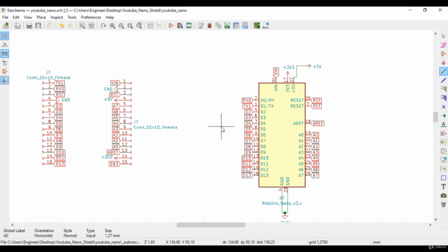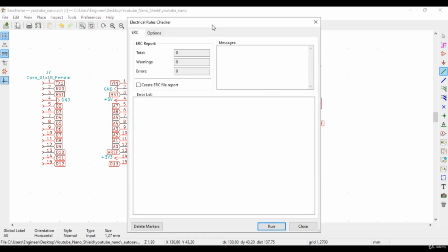Let's see if there is a mistake. That's why we use the ERC command here. It shows us logical errors or disconnected pins. I do not care much about logical errors because our circuit is correct. However, rules have been set for this entrance, such as this cannot happen.